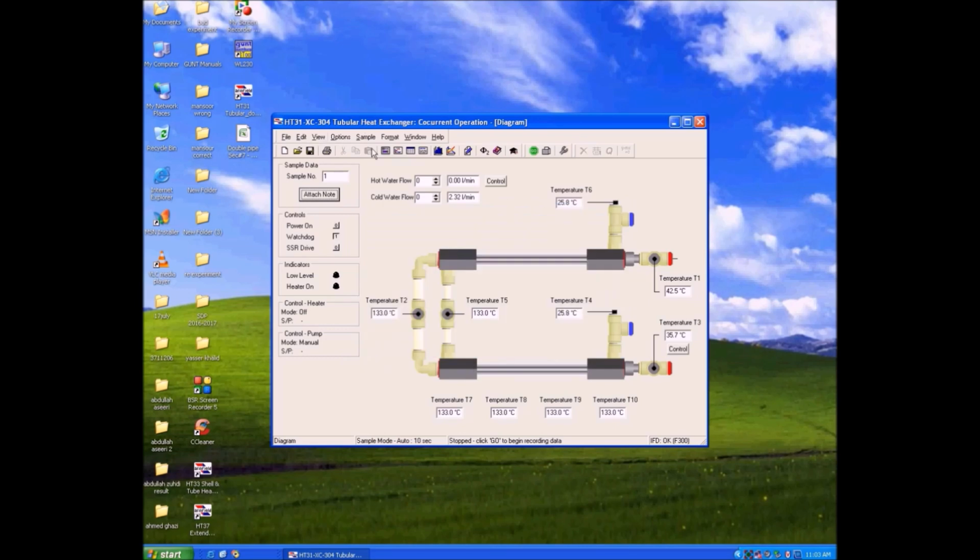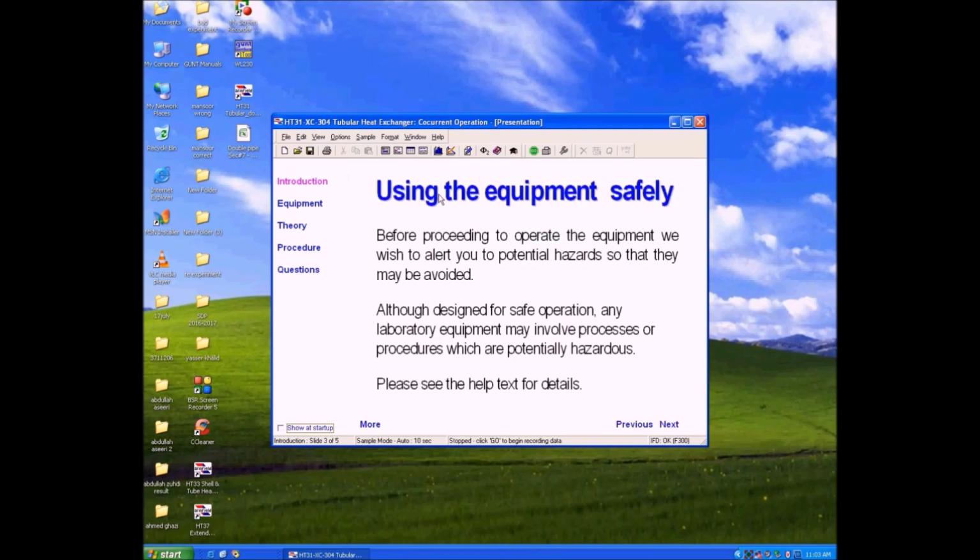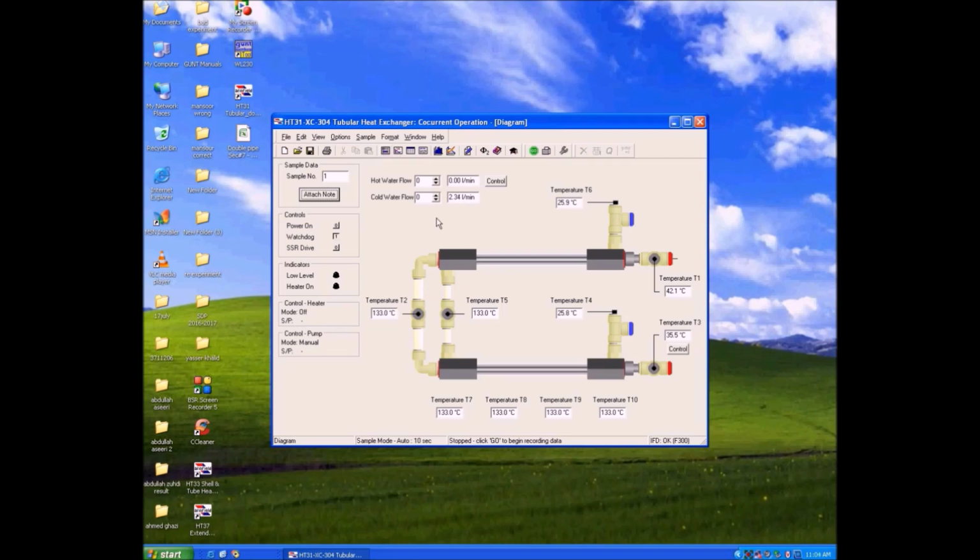click on concurrent operation, select power on, and view diagram, and then we'll adjust the heater voltage, which is the control shown at the red inlet and outlet. Click on the control and select the heater setting to 45 degrees centigrade and adjust the hot water flow rate, and we will repeat the procedure for 3 different heater settings. And at last we will save the Excel file by recording the data for 3 different settings.